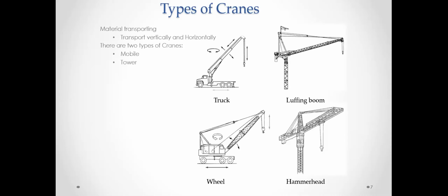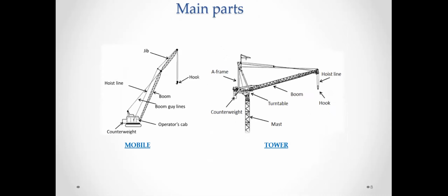On the other hand, there is another type of crane called the tower crane, and you can find them commonly in high-rise construction. They are the only type of crane that can be utilized once the building surpasses a height that can be reached by a mobile crane. In order to support the crane, it must be connected to the building. Some cranes can be on top of the building, and it will go up and up until the sky buildings.